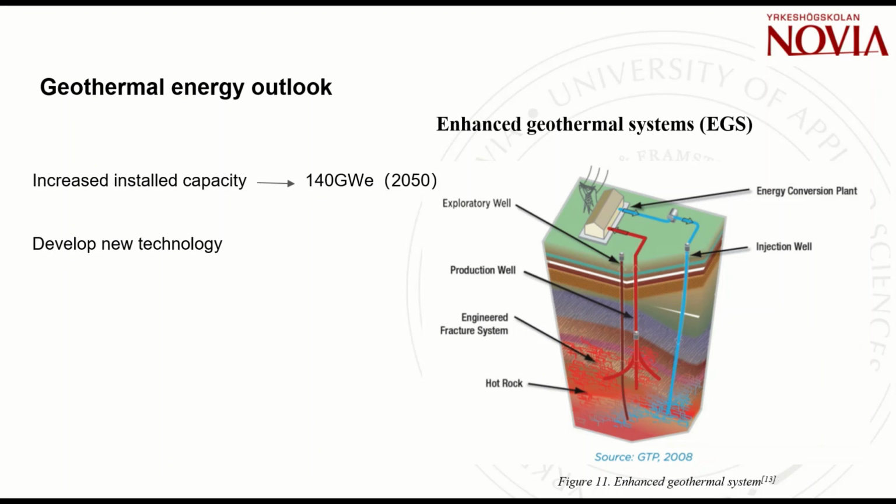Traditional geothermal power plants usually inject wastewater into reservoirs, but the natural cracks in the ground will be closed by some mineral deposits, resulting in poor permeability. However, EGS injects high-pressure water into those deep rocks, usually dry hot rocks, to reopen natural cracks. Then the water flows into the extraction well.